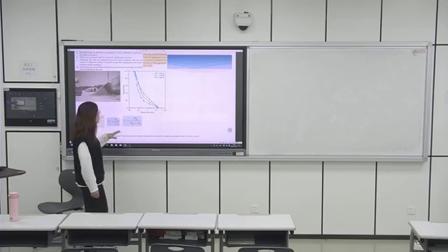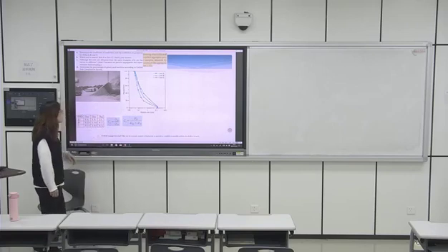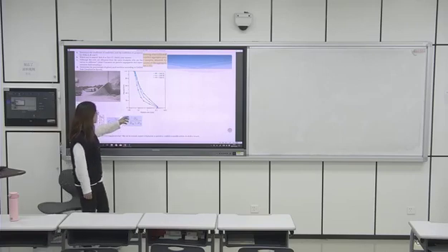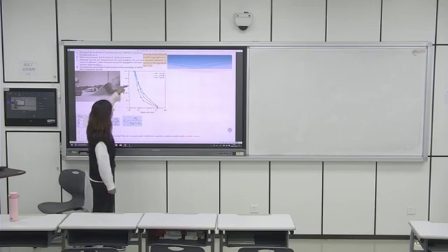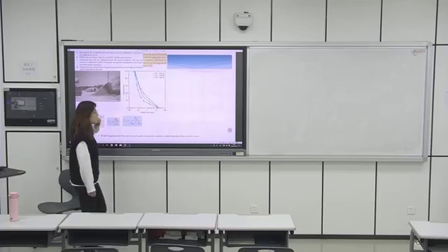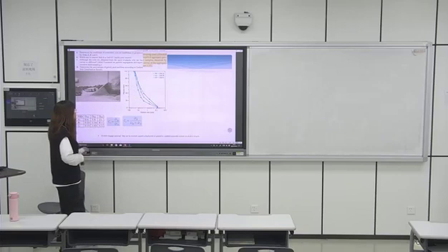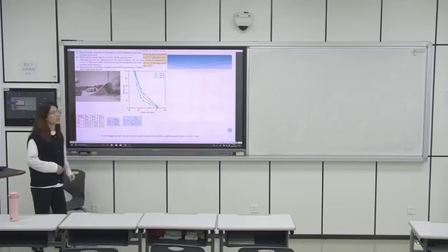So in here you need to know what D10, D30, and D60 are, right? D10, D30, and D60 are actually the particle sizes corresponding to 10%, 30%, and 60% passing. So if you know the definition, it is very easy to find the D10, D30, and D60 for soil A, B, and C, and then calculate Cu and Cc, right?